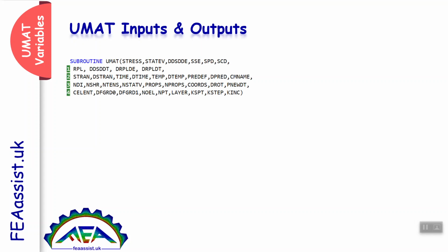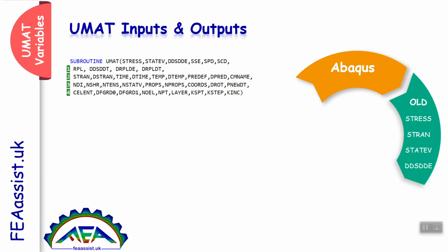VUMAT has some variables: stress, strain, TDS, TDE, and some other variables you can see here. Actually, all these variables are computed in Abaqus and transferred to the VUMAT.